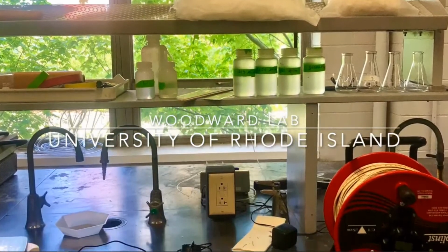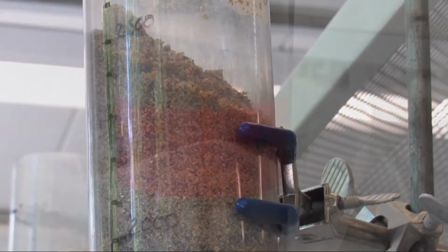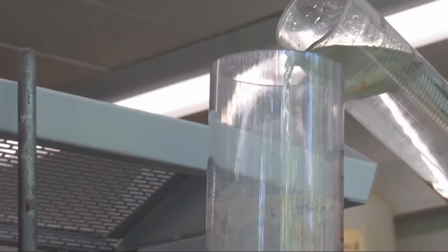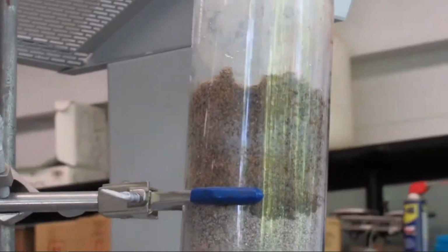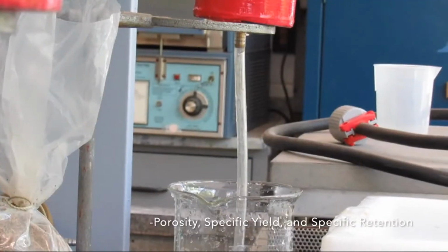These samples are taken into the lab, measured in columns with some sort of bucket to catch water. We pour water in the top of the sample columns until it is fully saturated and simulate its natural state as an aquifer, which would be compacted. Once in its natural state, we test for porosity, specific yield, and specific retention.